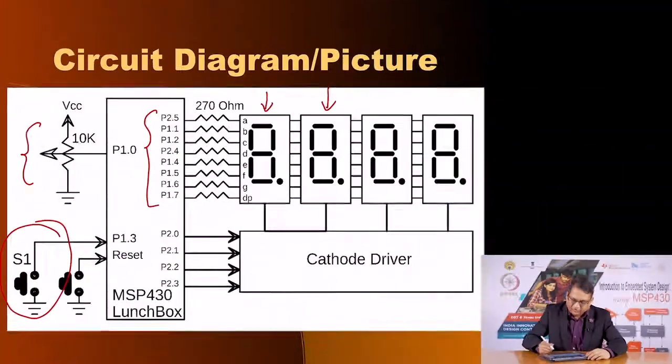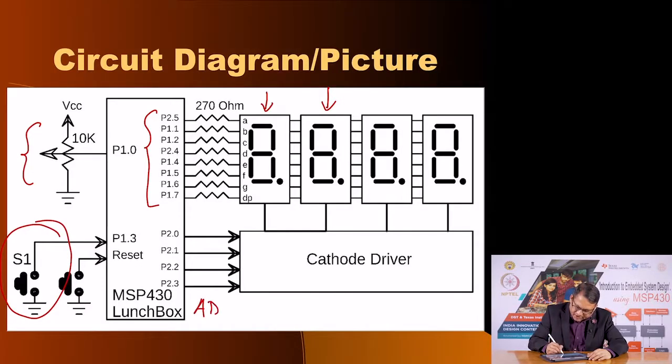We could map these values directly in terms of the time for which any given display is on at any given time. So, for example, if the setting of the ADC is such that the ADC value is 1, one way to deal with that would be, let me rewrite it, that the ADC count is equal to any given digit on time.